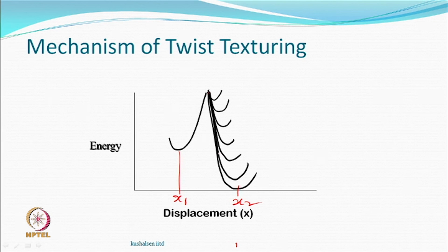How much time, what temperatures you may like to work, and you can bring down the energy level. Now, also you said you will cool it also. So, what do you have? Textured yarn, it is set, but actually there is no textured yarn. It is a multifilament twisted yarn which does not want to untwist. That is all.